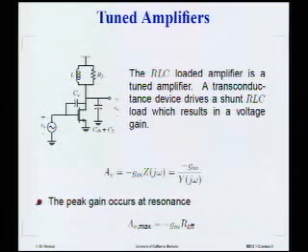So what are some of the advantages of this tuned amplifier? What have we gained by using an inductor? Why bother, right? Turns out that actually inductors, if you put them on chip, are quite large. They take up a lot of area. So you actually only want to use them if you really can get a benefit out of them. Otherwise, you try to avoid them. Resistors are much smaller, or transistor loads, active loads, are much smaller. They come for free. Inductors, though, take up quite a bit of area, so we don't want to use them unless they really are giving us a benefit.